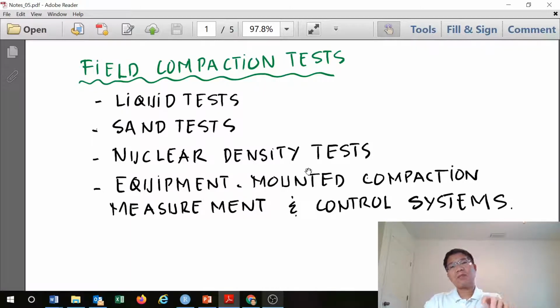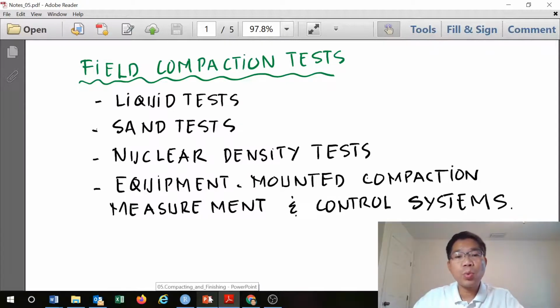In real time, they measure the density achieved and the water content achieved while we compact, so that we can adjust the number of passes, etc. We can adjust on site and make sure everything is in order, instead of the traditional method where we compact and go back to see whether it already meets the specification, and it may be too late, and sometimes it needs rework.